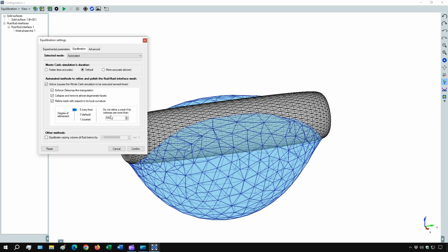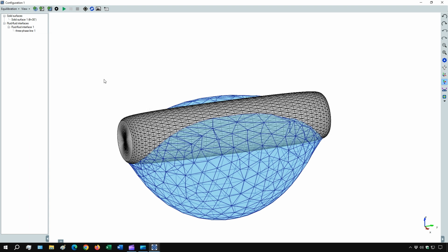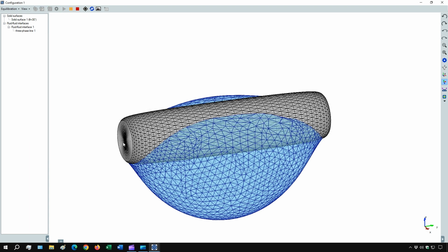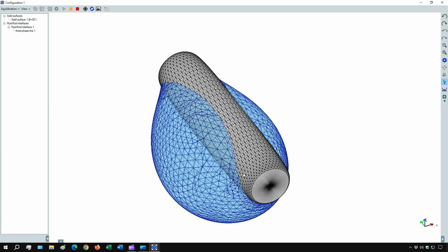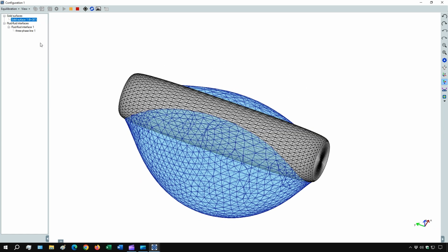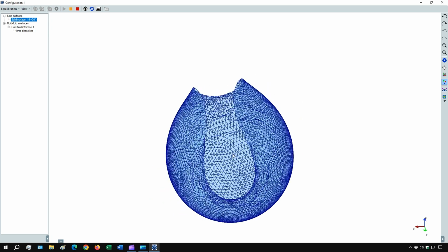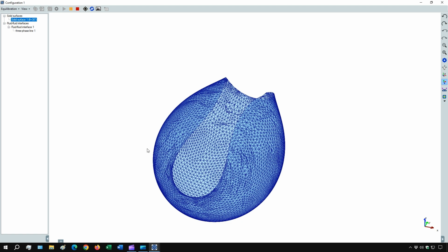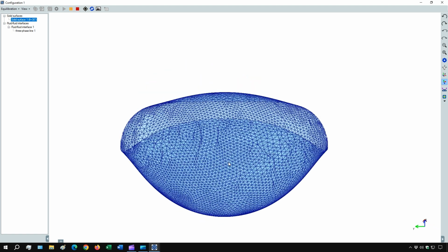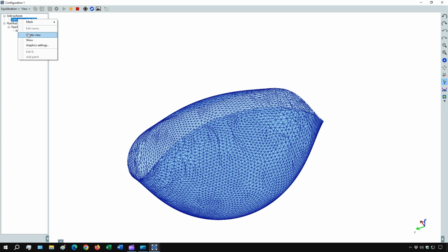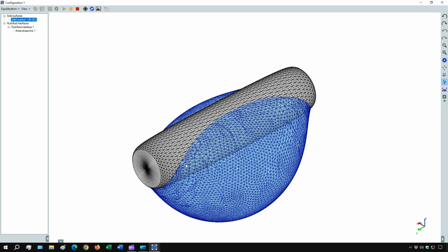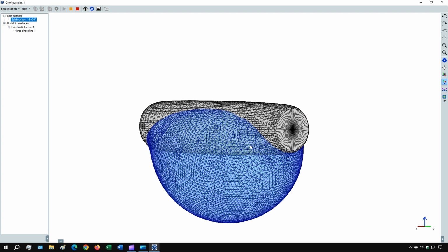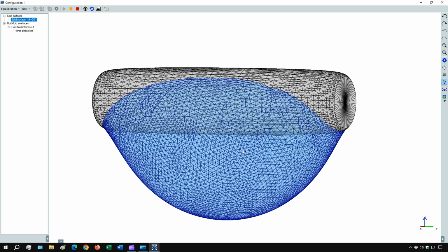Like we did before, let's launch another equilibration, just to further refine the droplet's mesh. In conclusion, we have found that, at the equilibrium, for a contact angle of 30 degrees, the water droplet can wet the cylinder with either the sessile droplet topology or the toroidal topology. That is, these two equilibrium shapes of the droplet are metastable.